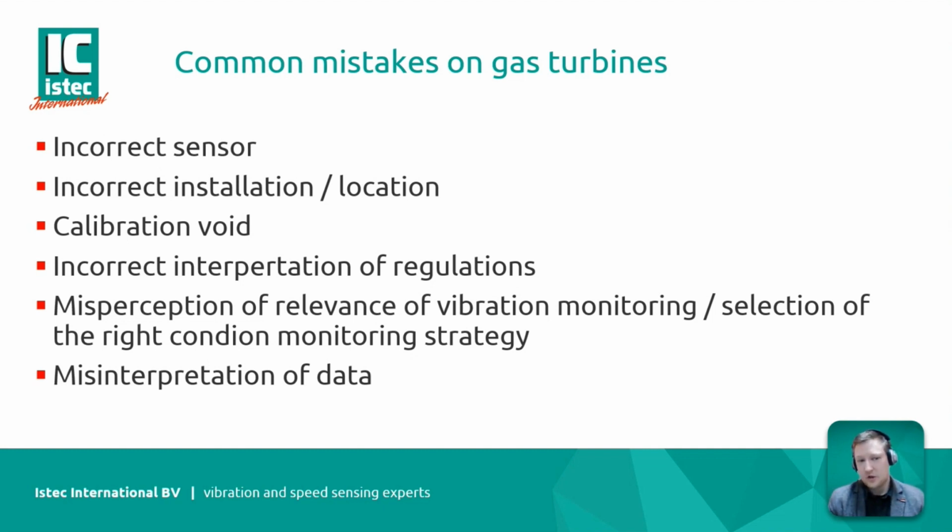Calibration, or periodically checking your sensor, is very important, because the sensor can become damaged. It can start to deviate, and it's used for protection and for monitoring. So there are big decisions being made based on data coming from that sensor. You want to make sure that the sensor is providing correct, accurate data. There are a lot of regulations concerning vibration monitoring and condition monitoring, and it's easy to get confused and to incorrectly interpret regulations.